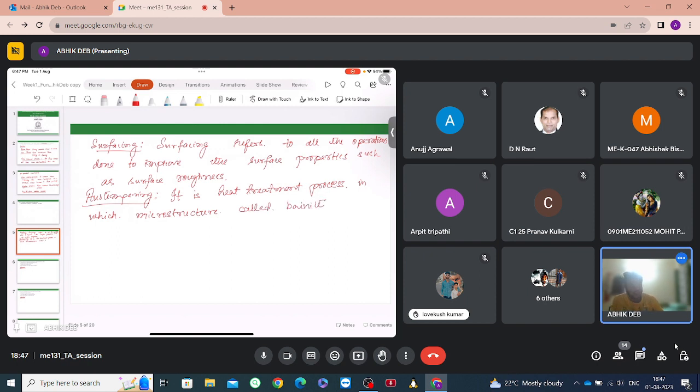If you have gone through the iron carbide diagram, you will see bainite on the right hand side below the pearlite regions. Due to the formation of bainite, ductility at high hardness is achieved. So this is an improvement of the properties of the entire component. The entire component will be heated, the phase will transform to bainite, and the properties of the entire component will be changed.